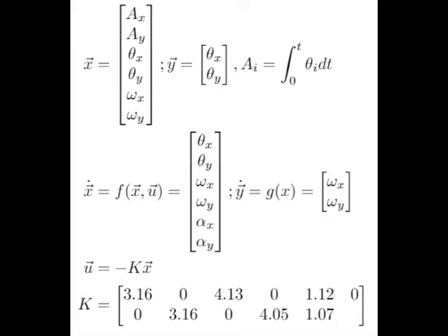Now that we have finished analyzing the system, we would like to consider a control solution that would stabilize the system, in which case we could simply consider a full state feedback controller, in which we just have the state variables influencing the gain with respect to their deviation from the reference signal.